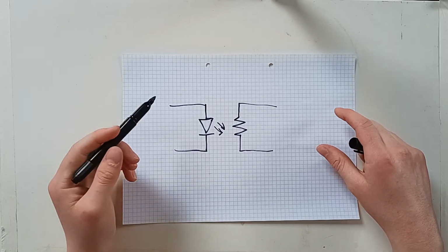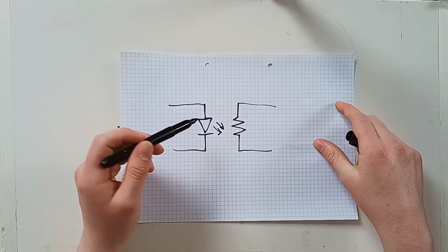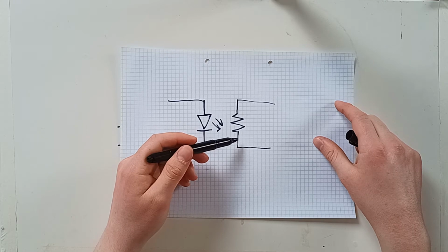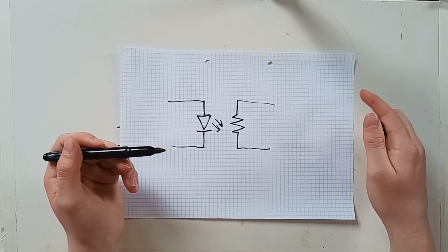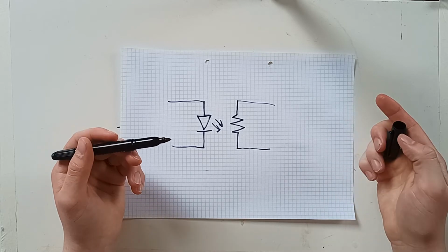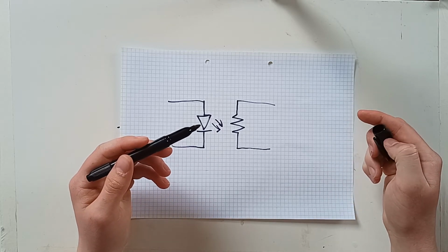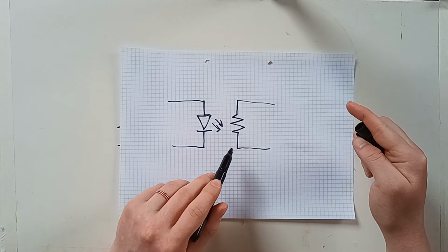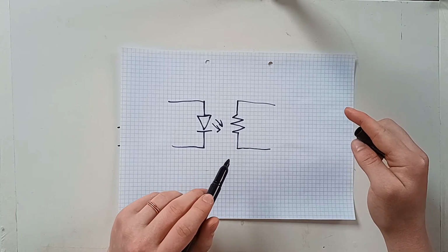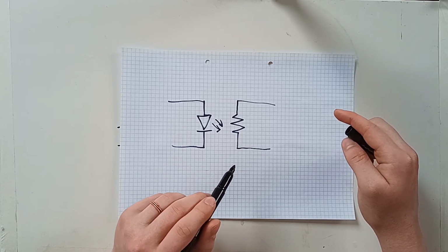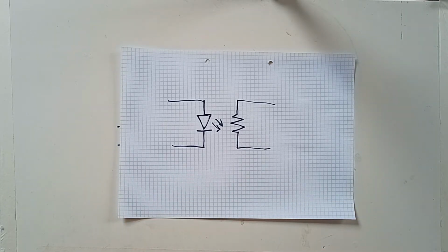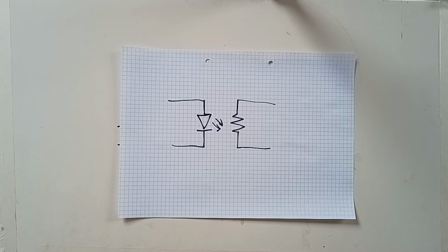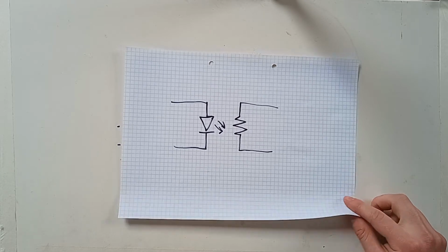However, there is an issue with this because LDRs can be very slow to activate just due to how they work. And there's not really much you can do around that other than getting extremely high quality LDRs or Vactrols, but they can get very expensive very quickly as they're a very niche component and they aren't used overly commonly in the world of electronics.